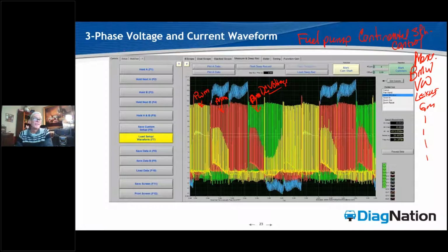And you guys are going to want to look this up because H bridge drives tons of your motors today, including your throttle motor. Okay, so the H bridge is going to be pulsing northbound and southbound current pulses to those magnets. It's doing it with 0 to 14 volt DC power, pulse width modulated.